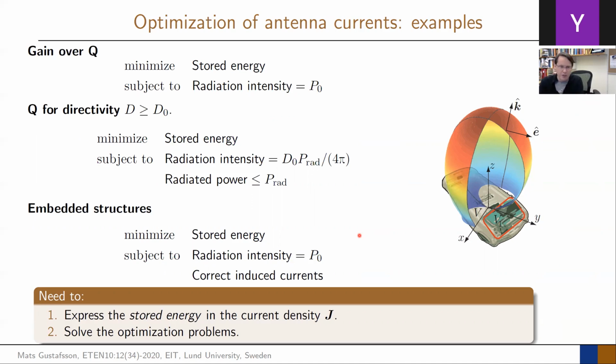And if we do that with an antenna, and we say that we, for example, want a large gain, so gain divided by Q in these cases. Gain should be high because that gives directivity. You want your Q to be low because that gives you bandwidth. Then you can say, can I maximize the quotient between gain and Q? And actually that you can do.